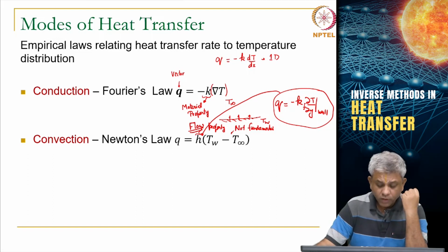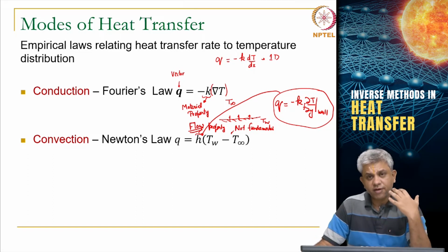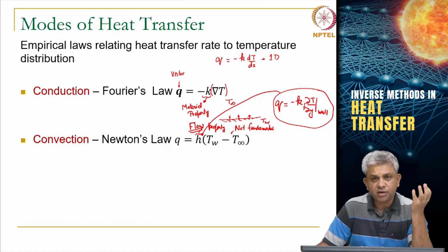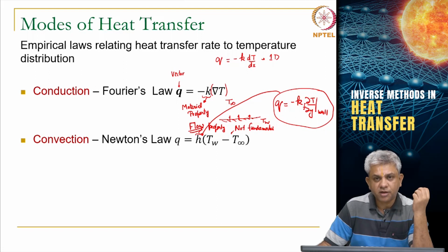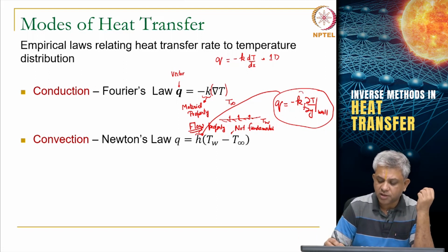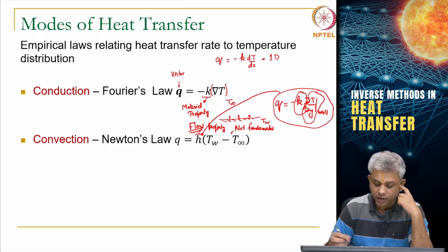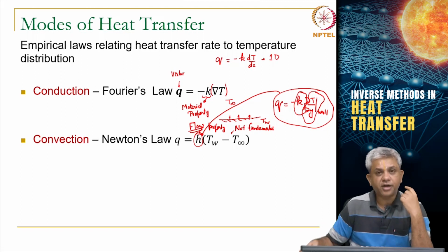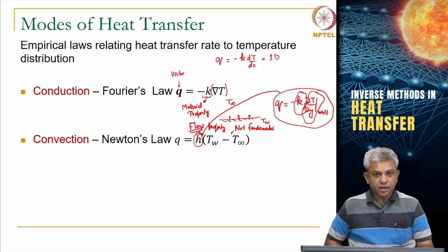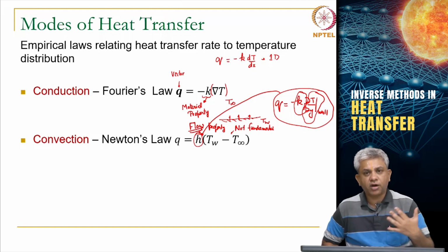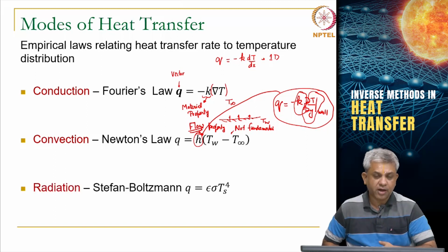So, all this is to say, if you solve an inverse problem, you have to be careful about what the known parameter is and what the unknown parameter is here. So, this Kf is a property of the fluid, but ∂T/∂y obviously is not a property just of the fluid, but of the entire flow, and all those put together determine h. So, you can't just say h of water is something, you have to say h of water for a specific flow is a certain value.